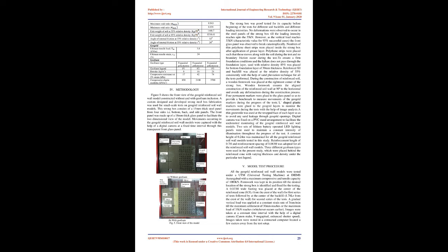Depending on the compressibility of the geofoam inclusion, the deformations would allow the reinforcements to develop friction with soil at the end of reinforcements. This may result in mobilization of the reinforcement strength at the face as well as at the end of the reinforced soil wall. So, the proportionality constant between wall face movements and footing settlement should reduce for the geofoam inclusion case.